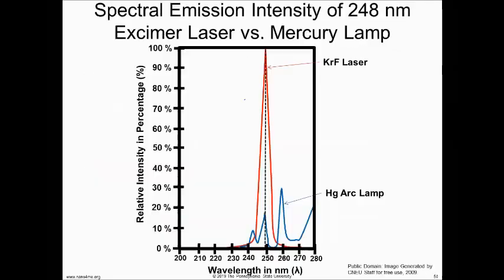Well, let me answer the question now somewhat. So we're going to use 365 nanometers. This is a mercury vapor lamp, and this is the energy peak right here. Do you see in blue? That's the energy peak. I'm going to apply the energy at 365 nanometers to my wafer, and that amount of energy times about 6 seconds, this peak times time, is going to give me the dosage, the amount of work to actually make my photoresist bonds break. Does everybody understand that?